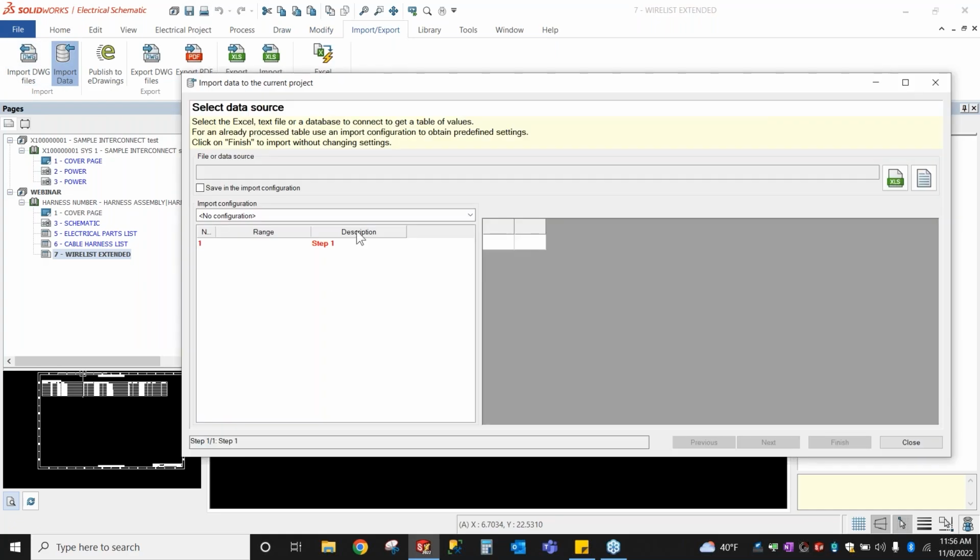And I'm sure there's got to be some content out there about this. But in here, this can actually go through and develop your manufacturer library from an Excel spreadsheet. The two things you must have is the manufacturer listed on each line, and then the part number on each line, and then there's whatever else you want to have included. So that'll get you the line items, and then you'll have to add in the circuits and terminals for that with this method.